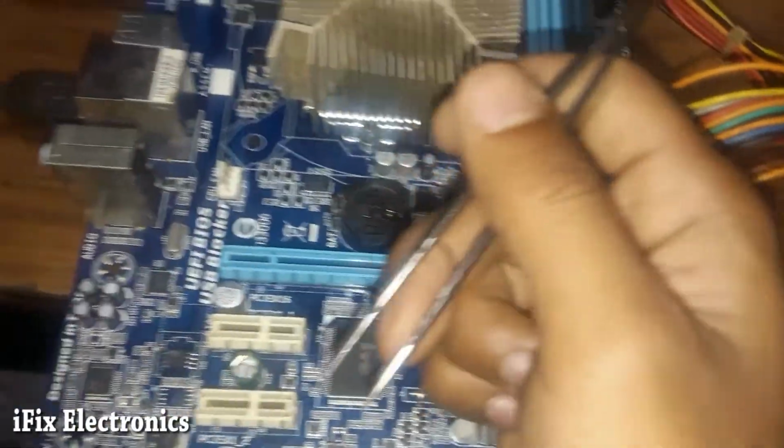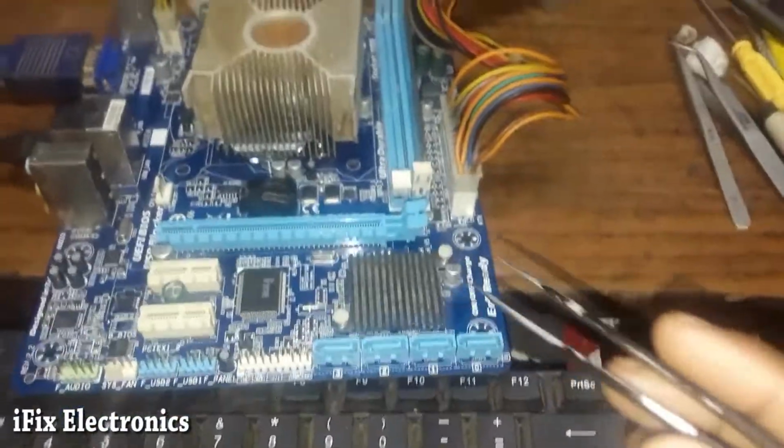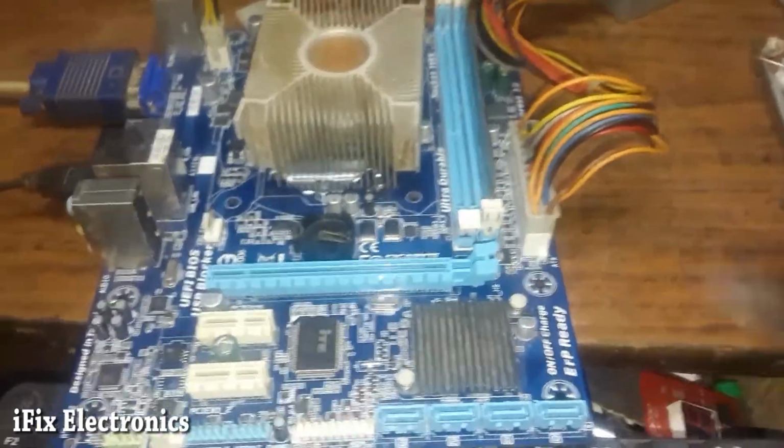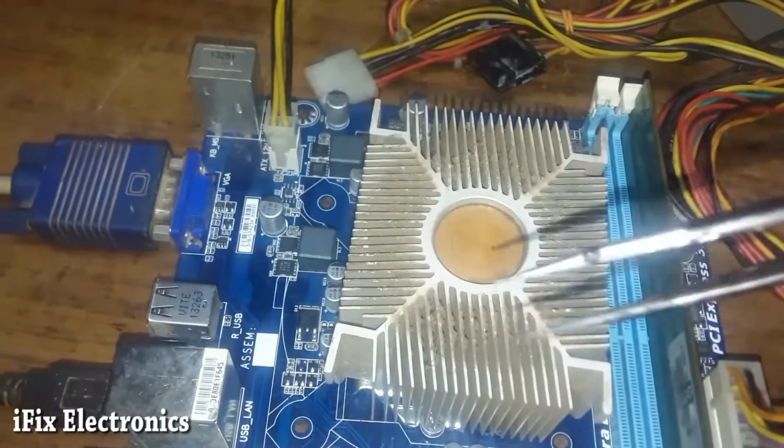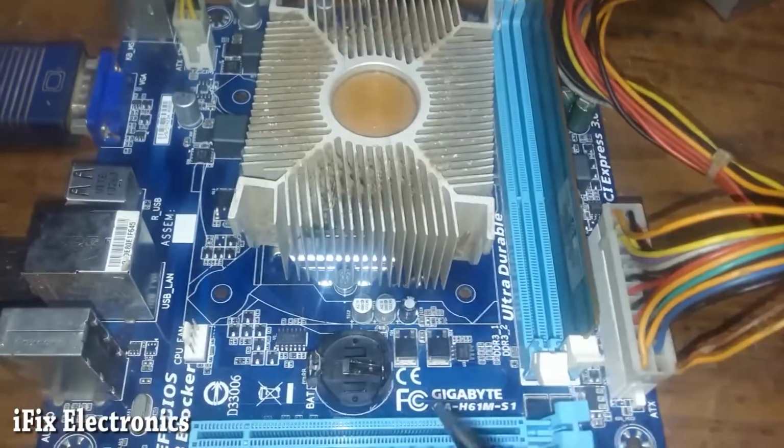Today I have received this Gigabyte GA-H61M-S1 motherboard. Initially, when I received it, I was not getting V-core voltage. I checked its enable and I was not getting enable also. So this is the model number.